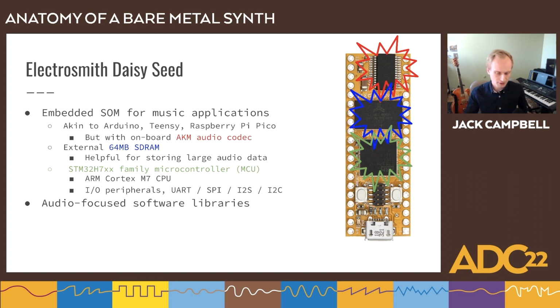Another nice thing about the Daisy is the software ecosystem that it provides. It has this thing called libDaisy, which wraps all of the STM32 HAL hardware abstraction library calls, so you can write everything in C++. You could before as well, but it wraps all the C stuff and offers audio-specific wrappers. Usually in a hardware library, you might get a pre-built UART library that allows you to use UART. But here you get a layer on top of that. You get MIDI support, which is great. You might not get that in a lot of other libraries. And audio is a first-class citizen in this library.